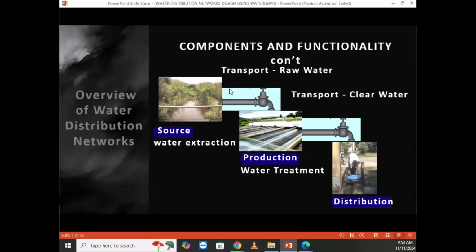Take this percentage of the calculated domestic water demand, and that will be the institutional water demand. Take this percentage, and that will be the commercial water demand. See, there's commercial water demand, institutional water demand, and industrial water demand. To me, all of those additional infrastructures are based on the population water demand.